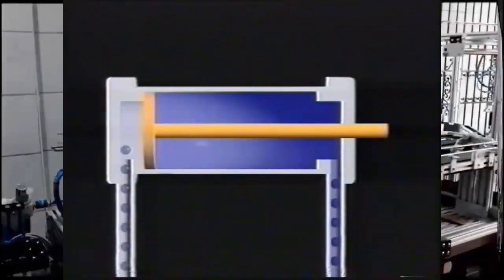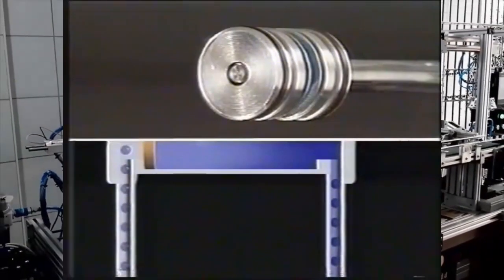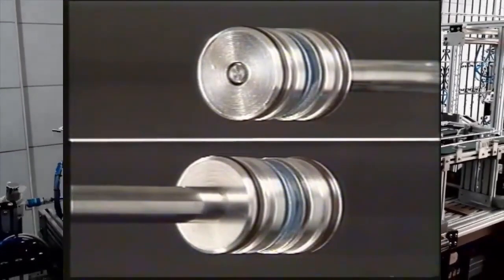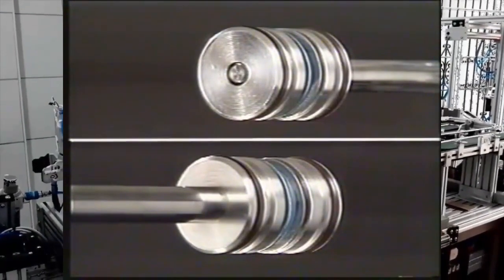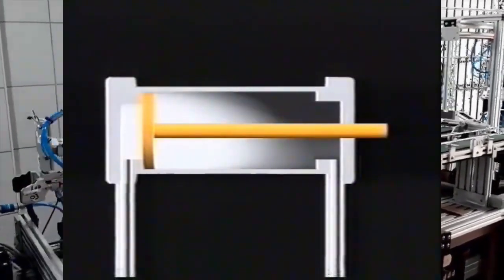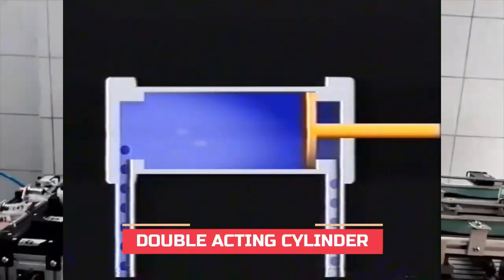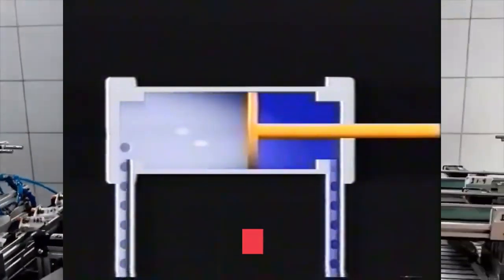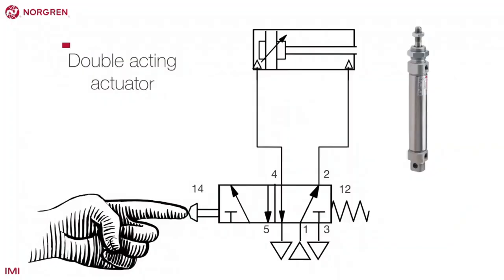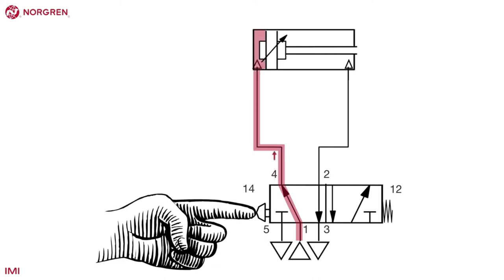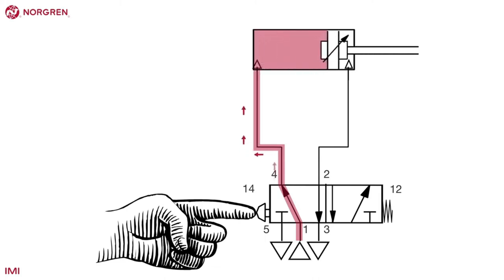A single-acting cylinder is one where output force is developed in one direction only. The piston is returned by a fitted spring. A double-acting cylinder is one where the thrust or output force is developed in both extending and retracting directions. A double-acting cylinder has a port at each end and moves the piston forward and backward by alternating the ports that receive high-pressure air. It is necessary when a load must move in both directions, such as opening and closing a gate.